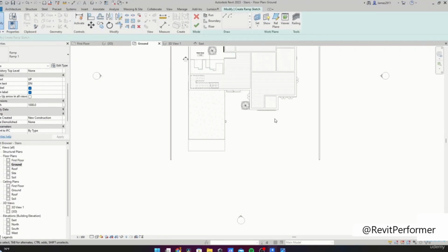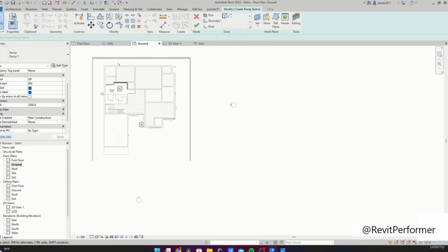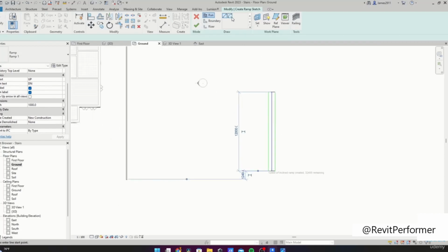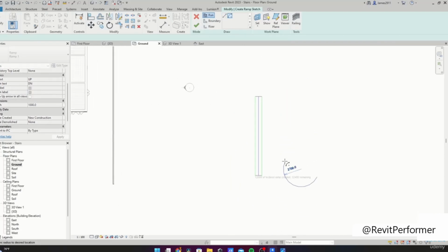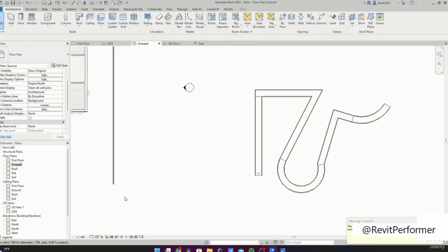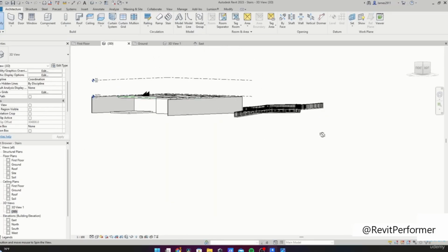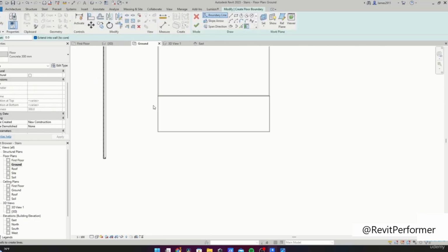Now, if you want a curved ramp, you can also do that. And if you double click, like over here, it'll automatically connect the ramps. Now, these are 1 by 12 ramps that take you to our ground. It will simply draw a floor. Okay, so now I have a floor. I'll simply draw a floor of concrete like this and click OK. I'll edit it so I match. I'll go to Align and I'll align it with the already present floor.